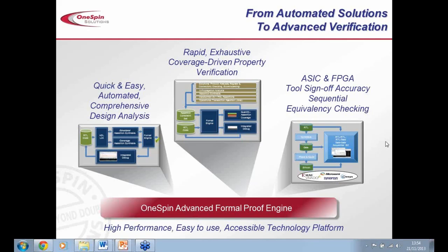And here we have a product called Quantify that really derives coverage information out of assertions. It's again push button. Someone has written assertions, of course. You run this tool push button, and you get a coverage matrix that you can also export in XML format to be integrated with the simulation matrix. We currently have statement and branch, and obviously there is more to do: expression coverage, toggle coverage.